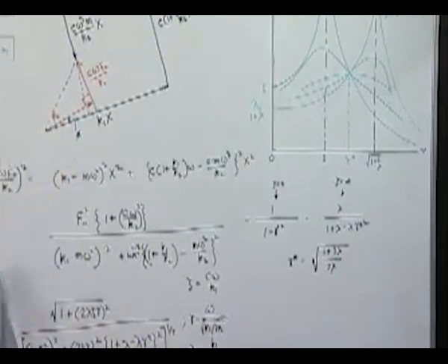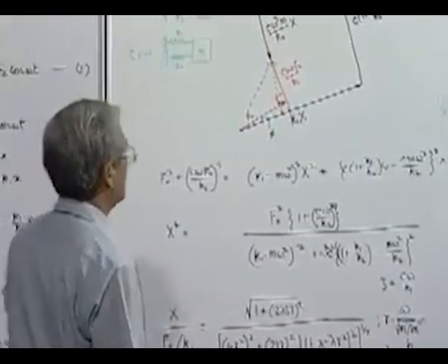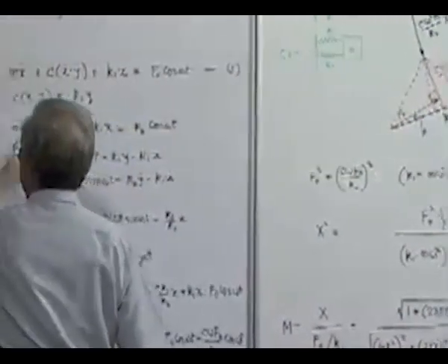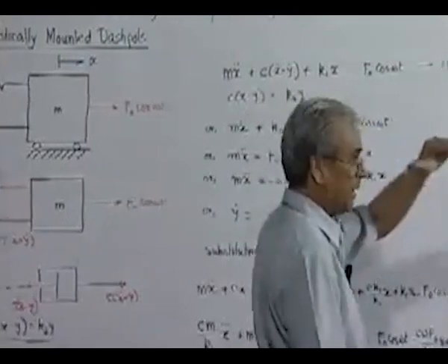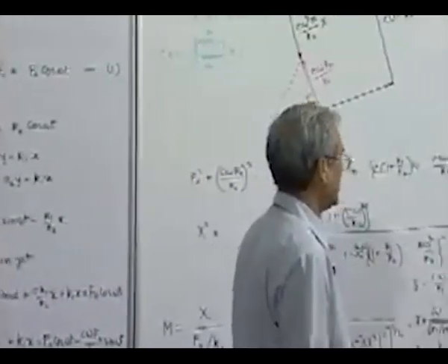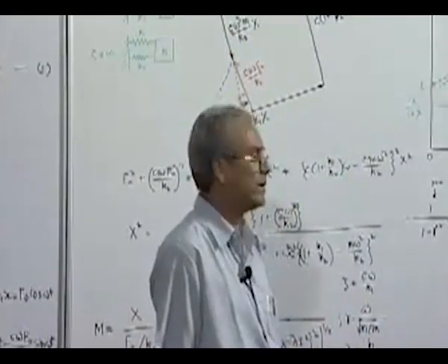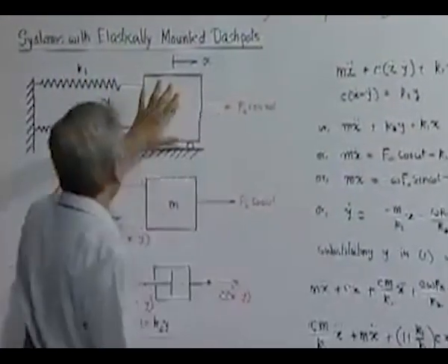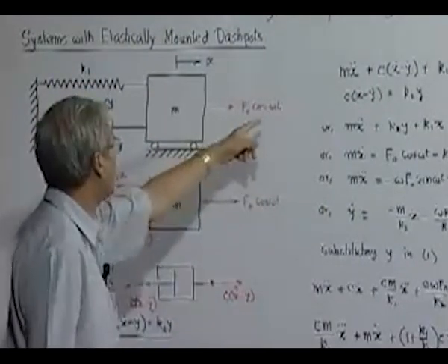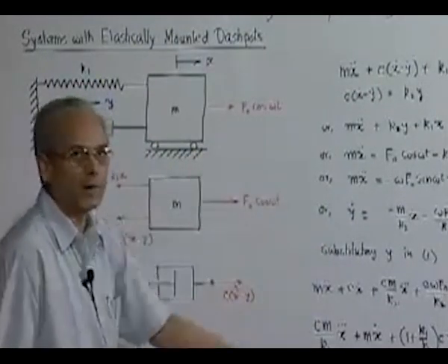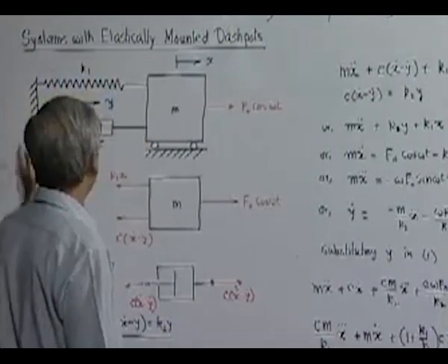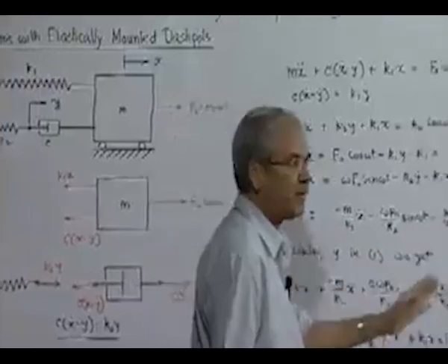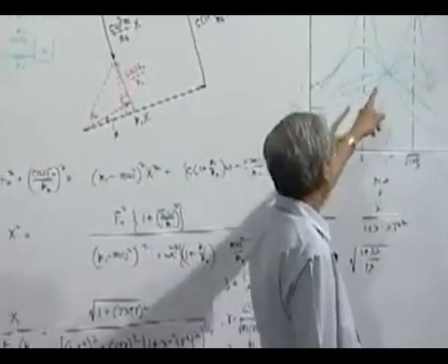So you will find that the deflection of the system in the whole range of different values of zeta will have to pass through this. Forcing frequency may vary. That means over the whole range, the peak value of the deformation or displacement will be kept to a minimum. So, this is another strategy which is a good example of design, that if you want to design something for which the frequency of excitation is continuously varying over a wide range, then we can always design it in a manner so that its maximum deflection will be minimum in the whole range if we design it in this fashion.